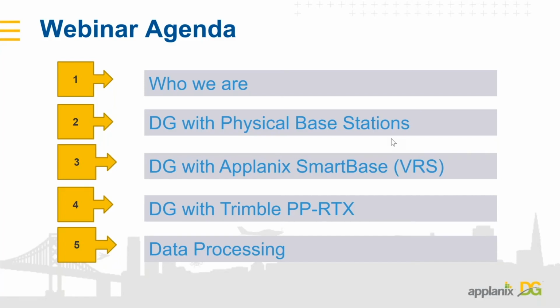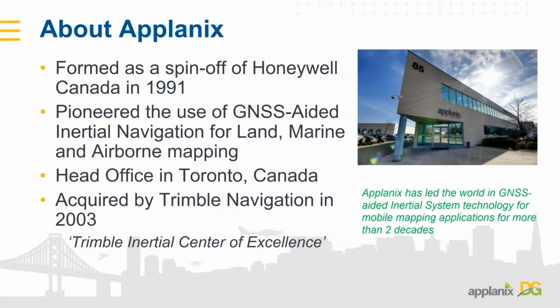Obviously, you're collecting data on your UAV platform. You're capturing your GNSS or positional data with your GNSS and your integrated IMU on your UAV platform. The IMU captures the orientation data. You take that along with your correction information. You process that through a piece of software, which Kurt's going to talk about later on. And you get your final products coming out of that, either an EO file, exterior orientation file, or we can actually generate a LAS file as well, which can then be used in other applications.